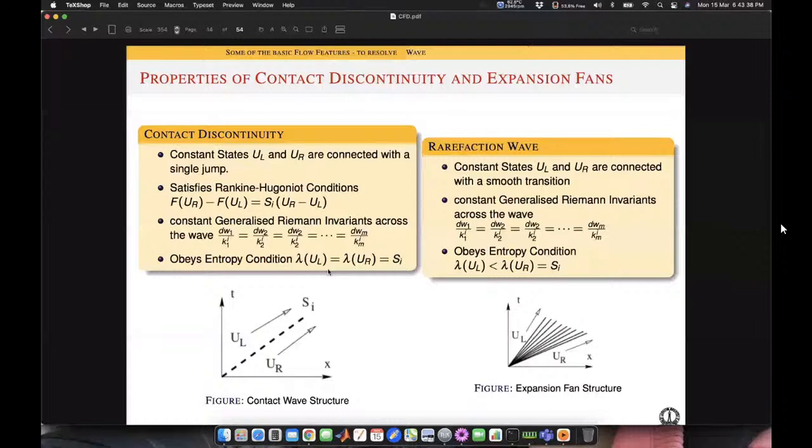So you see that the velocity with which the information propagates towards the right in the rarefaction wave is high, whereas the velocity of the vehicles moving in the front is less. So that's the information that you see in a traffic wave. You can see the same phenomenon in a traffic wave.